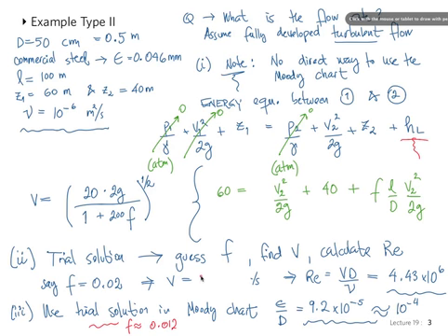The new Reynolds number is, what's the new Reynolds number? Ten to the 6. Okay. So now we can go again in the Moody diagram because we have the same value of relative roughness. Only the Reynolds number went up a bit. And what do you get?